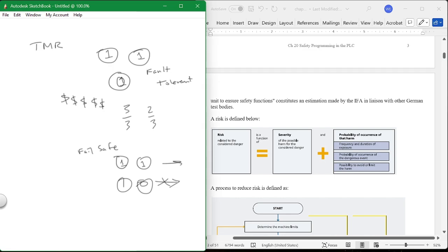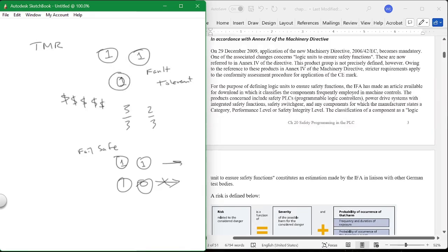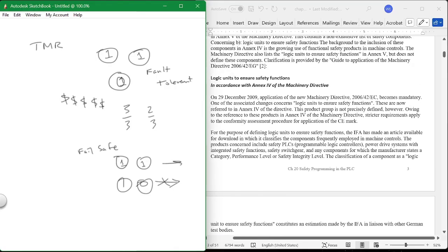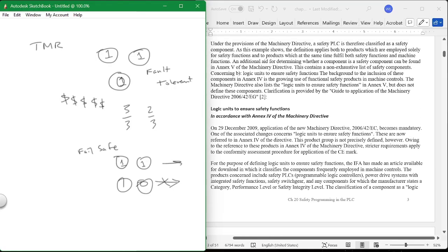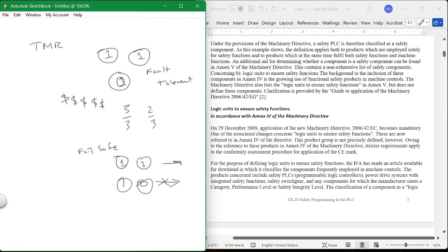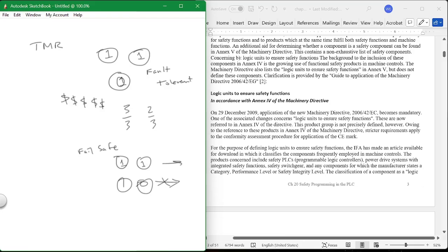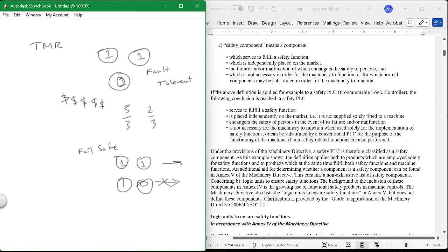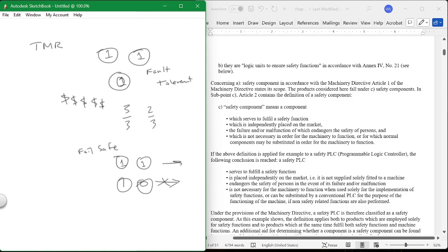I know, but on the other hand, you're also supposed to look at the machine directives and see if there is one like it, and you're supposed to copy that safety aspect. In other words, if there's supposed to be a guard on something, if that guard is supposed to have limit switches on it, if those limit switches are supposed to be redundant, all that is determined by these folk. So you don't have to think, you just basically find the example and copy it, and you're done.